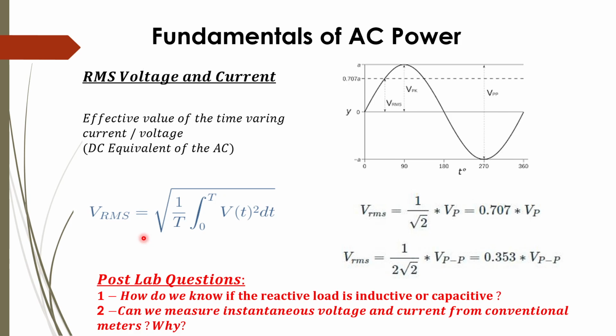number. If you have a sine wave of, let's say, 20 sin(50t), it's a time varying signal. Now we have an RMS value of a fixed number, let's say 30 volts, or maybe less than 20, maybe 18 volts or 17 volts. Those values won't be time varying, unlike the AC ones. Despite this, VRMS would show the DC equivalent of that AC, which is time varying. So that is how it is useful for us.